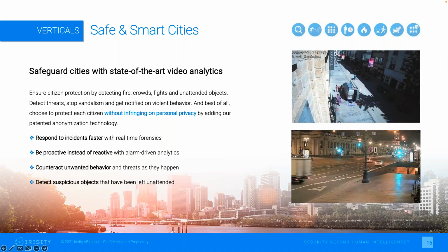From the Safe City perspective, we also enable the opportunity to investigate whether barriers could be removed, and these could be central barriers between roads. We did various projects where we understood the number of vehicles coming down a road and where people were crossing the actual intersections, jaywalking for instance, and whether taking a barrier away would increase or decrease the jaywalking. In fact, when you take a barrier away, the jaywalking increases tenfold, which increases the risk of accidents, not just to the people crossing the road, but also to the drivers of the vehicles. So these types of things are all taken into account.